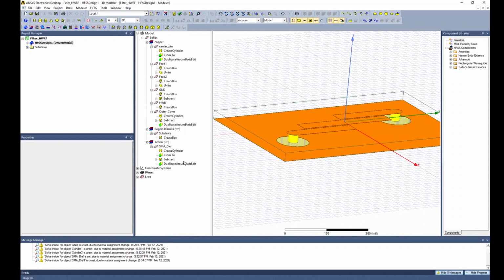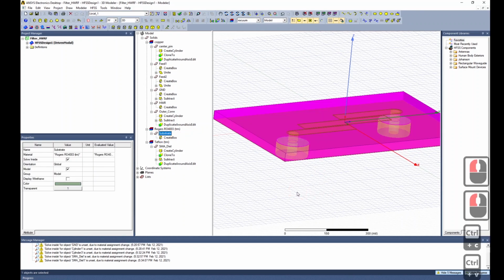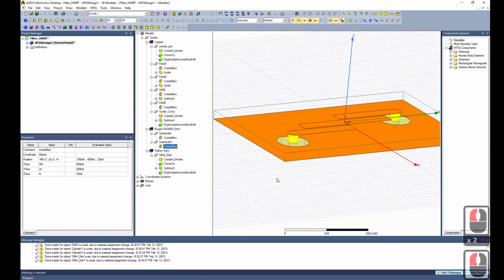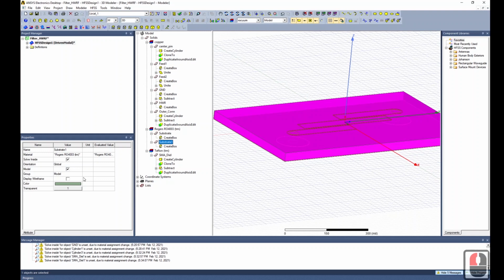So for simplicity, let's just create it out of the substrate. Now, to truncate the simulation domain and just make the simulation run a bit faster, I'll be using radiation boundary conditions in this simulation. It allows you to make the domain a bit smaller compared to potentially using PMLs or using a finite structure surrounded by free space and then some PML. When you have microstrip structures like this, which pretty much couple energy from one port to another, this is a pretty good way to model which allows you to reduce your simulation domain.